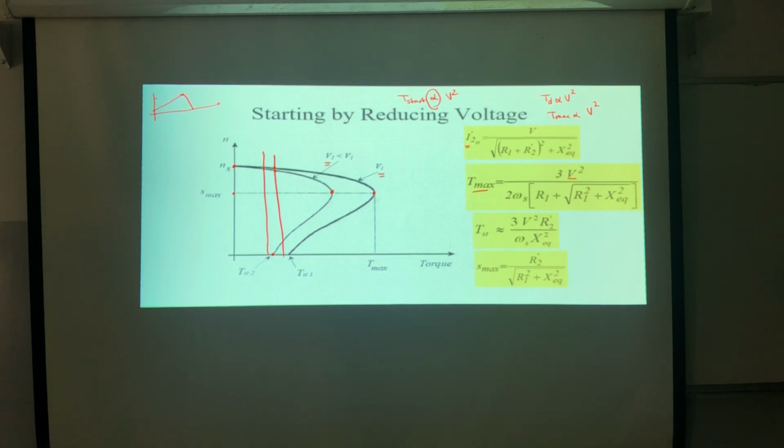So nowadays, no one uses this method. Why? The first thing, I need a mechanism in order to change the voltage. I have a mechanism, yes. Someone says I can use an auto transformer. Someone says wait, auto transformer means that you need a human to change the turn ratio in order to adjust the voltage. Okay, someone said that I will use voltage control power electronics. You say okay. But if you use power electronics for only gaining a small advantage, controlling the machine in a very, very narrow region, it's not worth it.